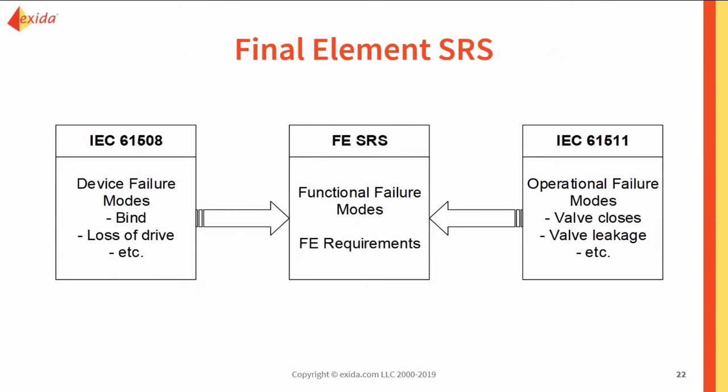As I mentioned, one key piece of information is the SRS, or the Safety Requirements Specification. We have a safety requirement specification from IEC 61508. It's the information about how the device is going to act, how it might fail in different environments and different operations. It could bind, it could have a loss of drive, it could have dangerous failures or safe failures.